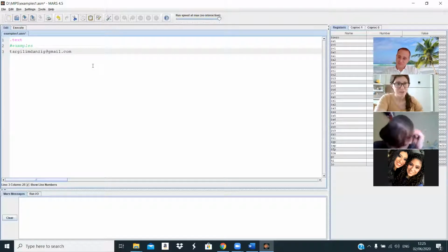Okay, so when numbers are signed, how we would check for an overflow in digital systems was we would see if the two numbers you're adding are the same sign. If they are, then the most significant bit of the result has to be the same bit. And if they're not the same sign, then it could be anything and it's not an overflow. So it just didn't seem to match up with how we were checking an overflow here. Because that was adding and this is multiplication. Oh, okay. So it's different rules with multiplication and adding.